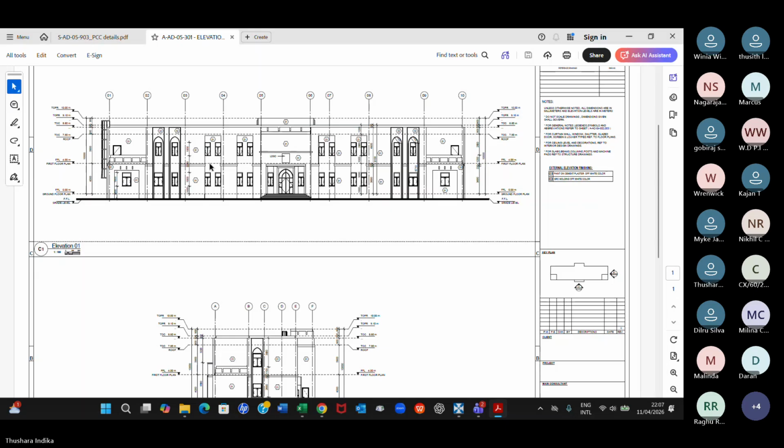Now, you have the same thicknesses maybe on the second floor. Third floor also we have the same thicknesses, or maybe slightly different thicknesses. Now, let's say in the first floor you have to create 5 dimension groups, right? And in the second one you have to create another 3 dimension groups, so altogether 8. And if you have about a 35-story building, you will end up creating about 40-50 dimension groups. So that will be a headache.